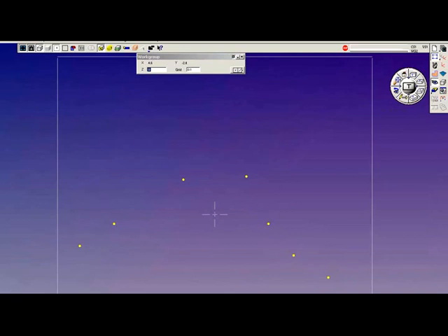Just like that. Then I'm going to generate a curve through those points. 3 choices. Polyline generates lines between the points. Spline fit generates arcs between the points. And spline control points, I would generate a B-spline and use control points to control the shape. The tolerance setting, 0.001, and I've selected spline fit for the best fit, and then the curve selection could be